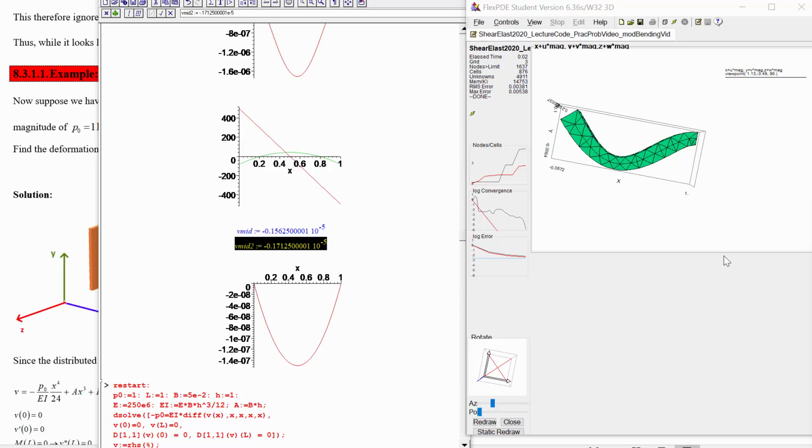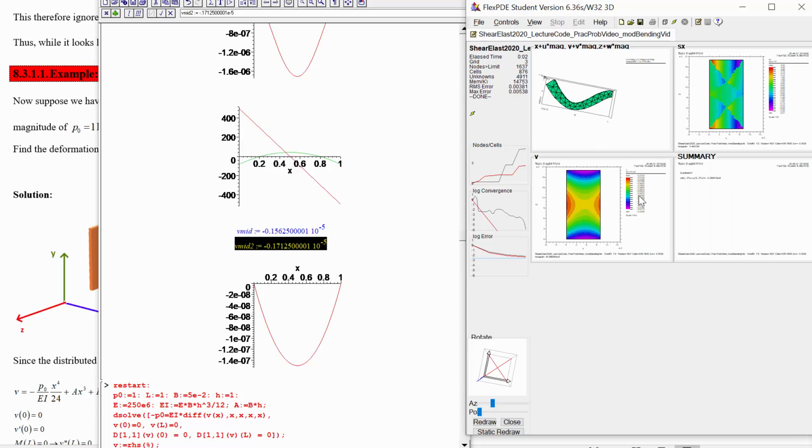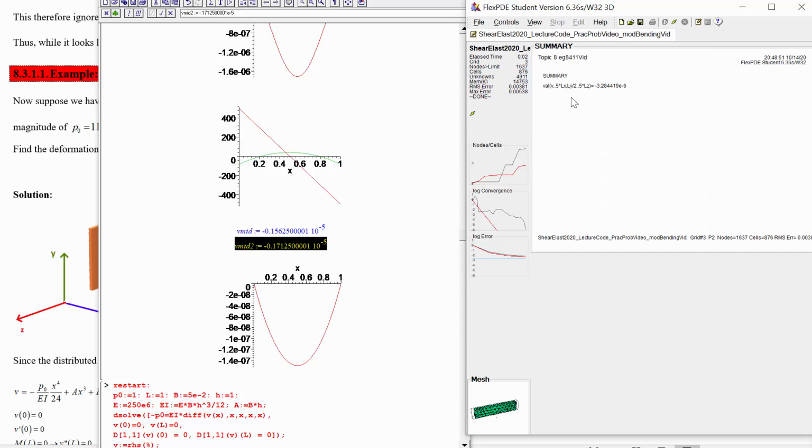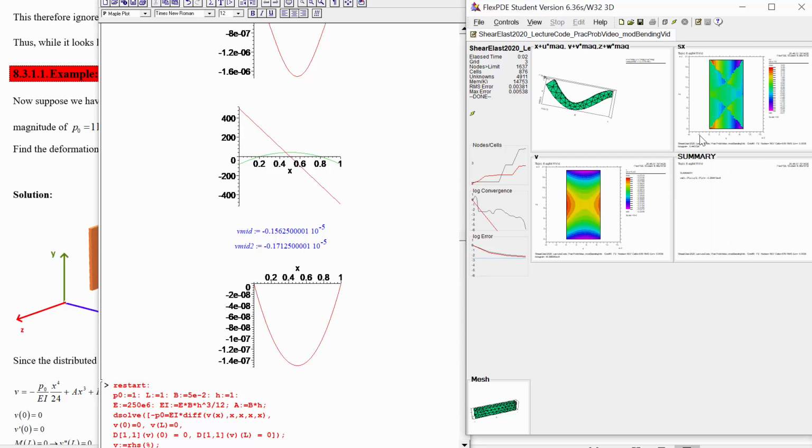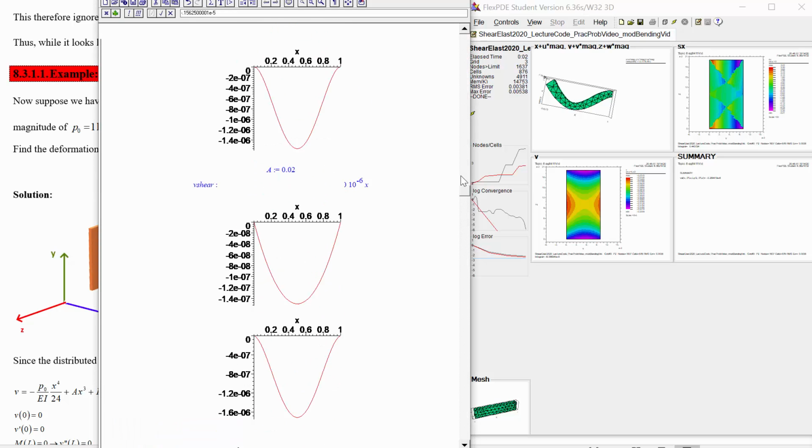So one other thing we can do is compare the displacement we get at halfway with this to the displacement we would have calculated if we set it to a pin support on the left in Maple. So this is no longer the point of peak displacement. The peak displacement occurs a little bit to the left of the middle there. Let's see what it is in Maple.